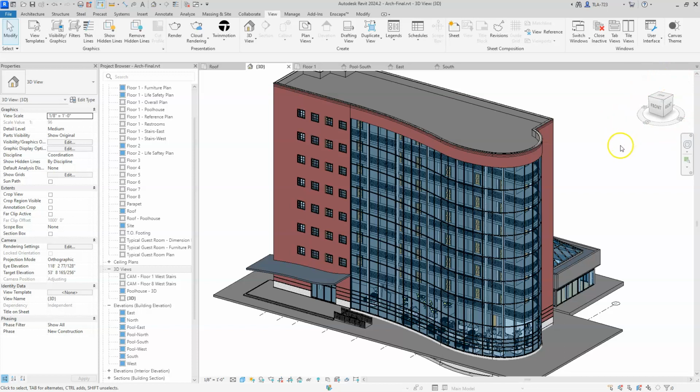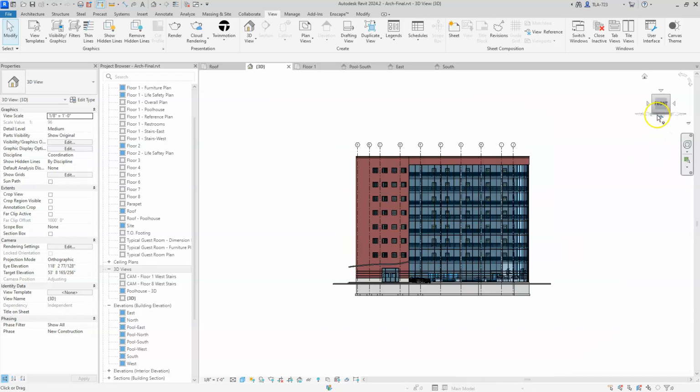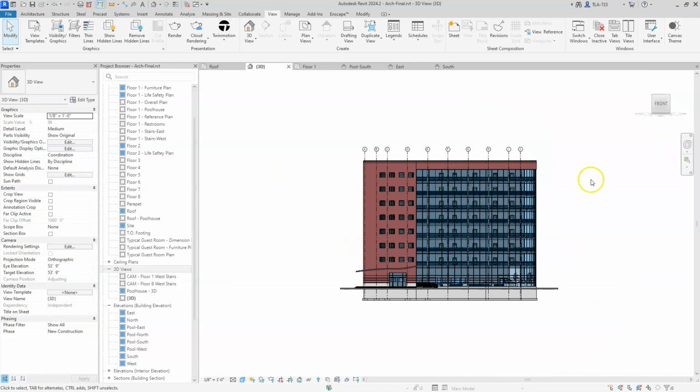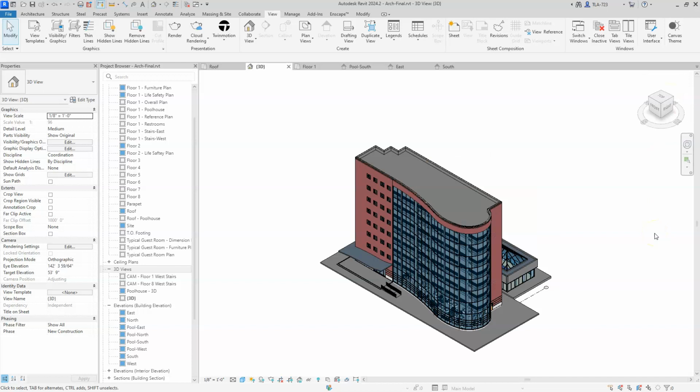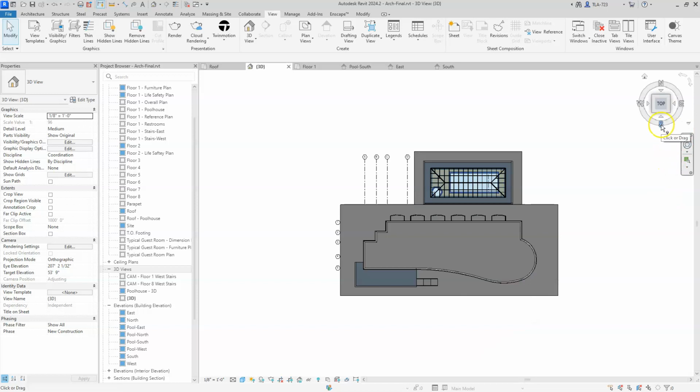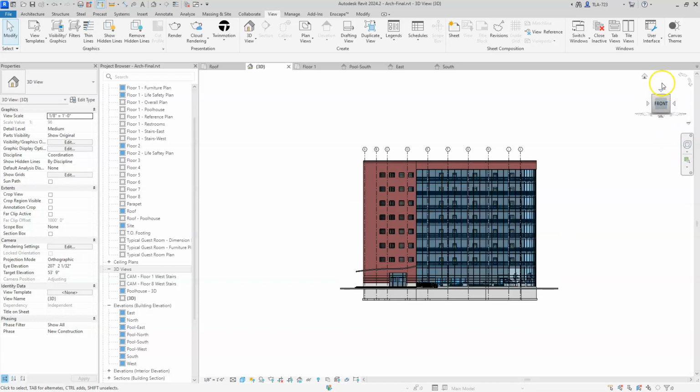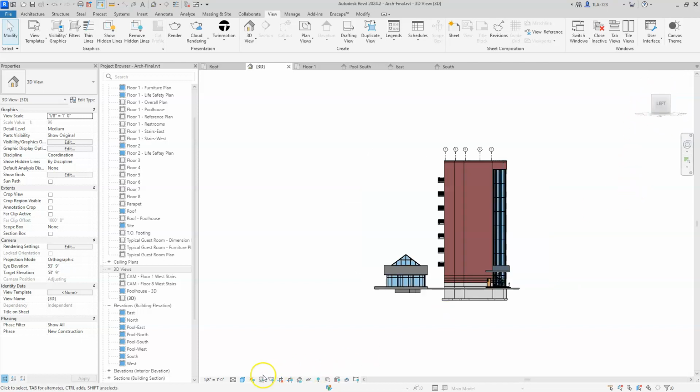Typically most useful in a 3D view, maybe even only available in a 3D view, but if you click on the various highlighted elements of the view cube, it'll take you to an isometric view of that space. So if I want to look at this directly from the front, I can just click on this. It'll automatically reposition the model so that I'm looking directly at it in a 3D view. I can click the corner, and it's going to take me to sort of a 45 isometric view of it. I can switch to a top view, so forth and so on, right? And these different arrows are kind of doing similar things with this.